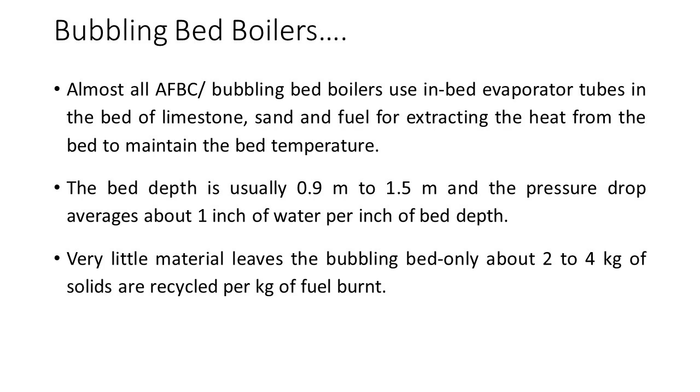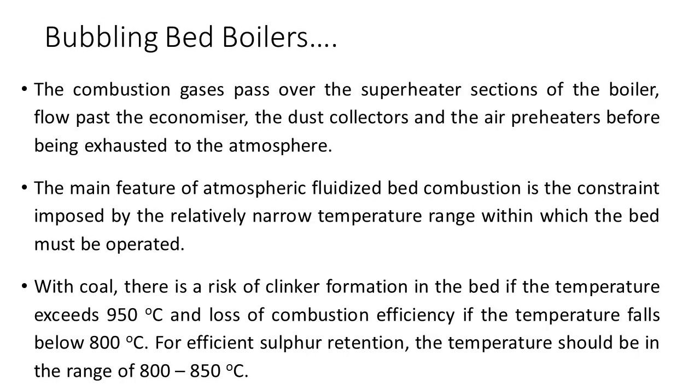The bed depth is usually 0.9 to 1.5 meters and the pressure drop averages about 1 inch of water per inch of bed depth. Very little material leaves the bubbling bed. Only about 2 to 4 kg of solids are recycled per kg of fuel burnt. The combustion gases pass over the superheater sections of the boiler, flow past the economizer, the dust collectors and the air preheaters before being exhausted to the atmosphere.